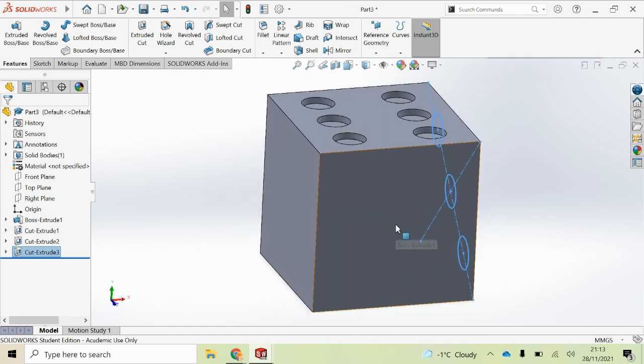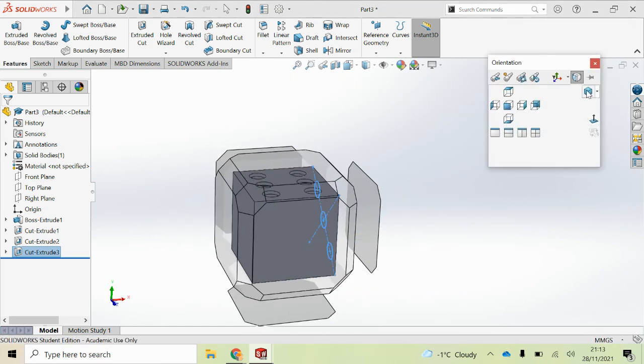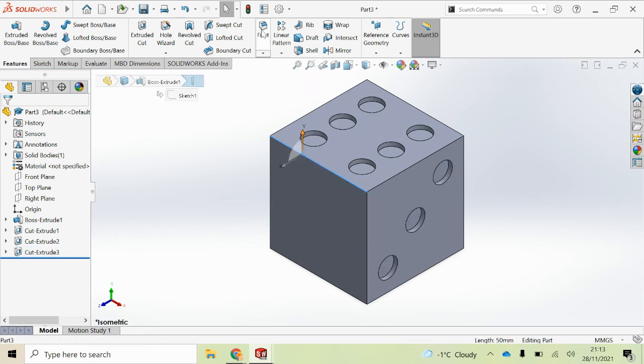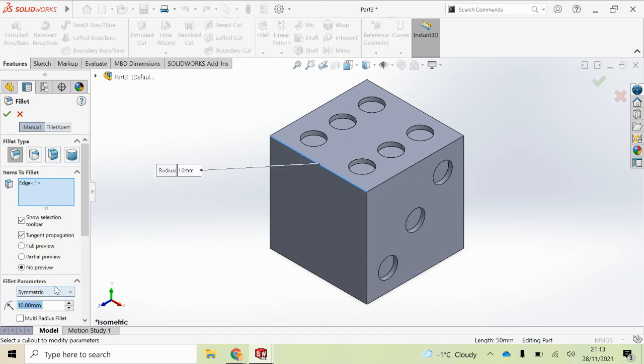The one other thing that's worth mentioning is applying a fillet to the edges of your cube. Now for that to work, we've got the button up here called fillet. We can change it to a chamfer, but we'll talk more about that in a future lesson. So we're going to look at a fillet, otherwise known as a radius. Now for this to work, what we need to do is click the fillet tool. I'm going to go for a fillet that's quite small,